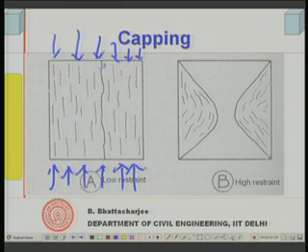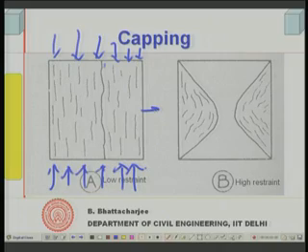So, it does not restrain the concrete from expanding along this direction, and therefore the crack is parallel to the direction of loading, as it should happen, because we have said the failure mechanism of concrete cubes is tensile failure along the transverse direction. So, the strain can reach the ultimate strain early throughout the specimen, nothing is restricting it, and therefore you see a vertical crack and it fails at a lower load.